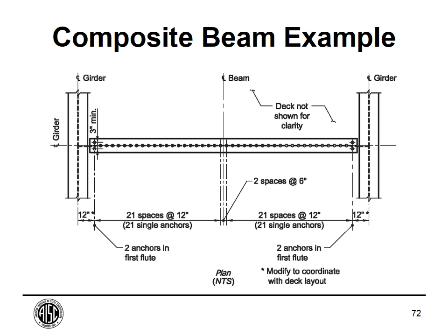So this is straight out of the example problem, the original example problem. We have the stud layout showing that we have 23 studs on each half of the beam, but 2 are doubled up. We couldn't quite fit enough studs in there, so we added 2 at the end. So they're going to have a little bit less strength than the other 21 studs.